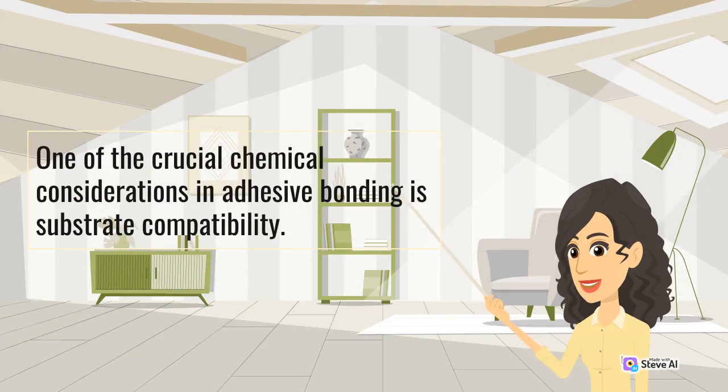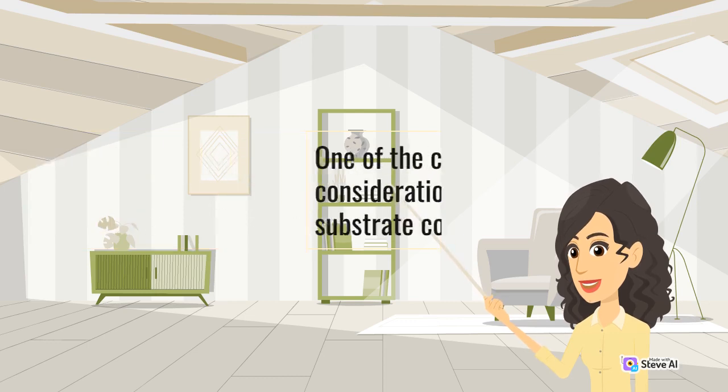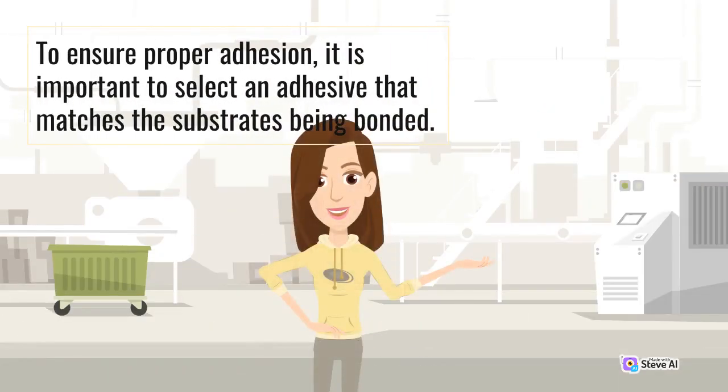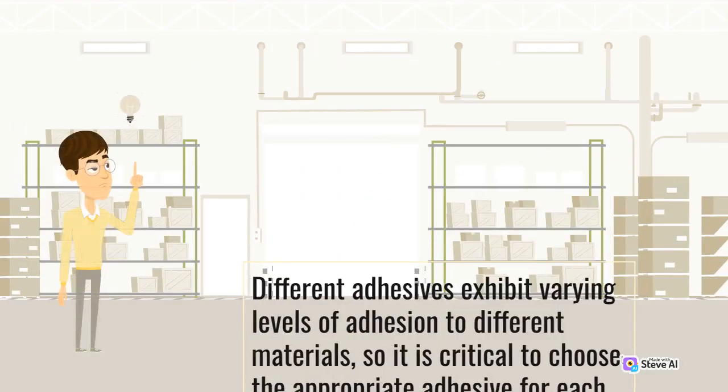One of the crucial chemical considerations in adhesive bonding is substrate compatibility. Electronics involve a wide array of materials, such as metals, plastics, ceramics, and composites, each with its unique chemical composition. To ensure proper adhesion, it is important to select an adhesive that matches the substrates being bonded. Different adhesives exhibit varying levels of adhesion to different materials, so it is critical to choose the appropriate adhesive for each component.